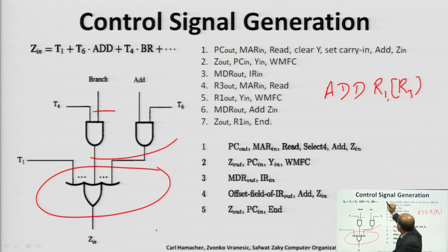This instruction is fetched. So, the first 3 steps are required to fetch the instruction from main memory where this instruction is stored, and this is the operand fetch step, meaning the second operand is given in a memory location whose address is given in R3. So, you can see various commands are generated, or various control signals are issued, by this particular unit. When a particular signal is to be issued, that depends on various inputs.